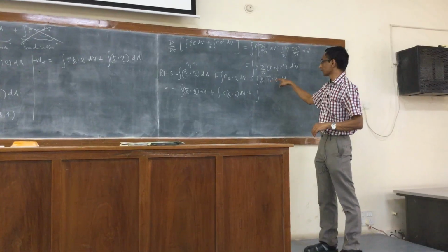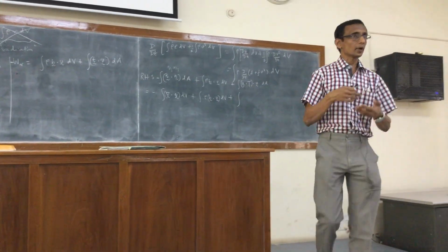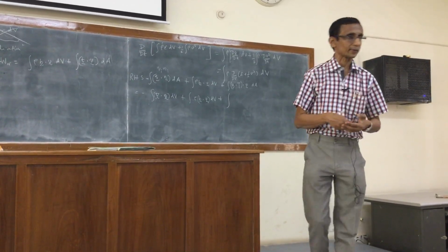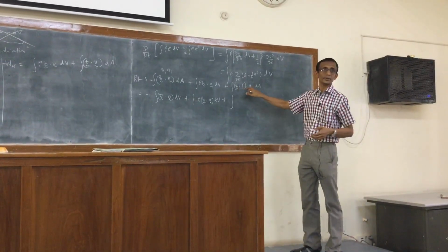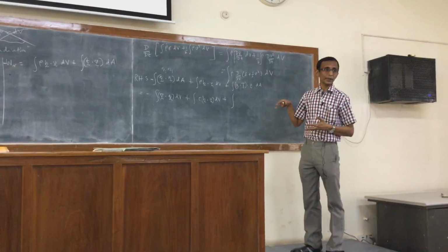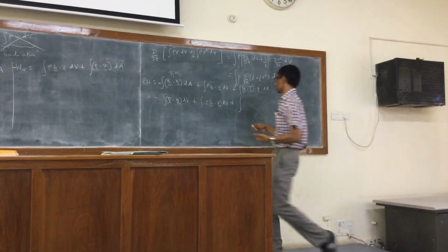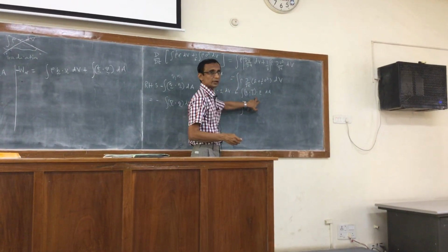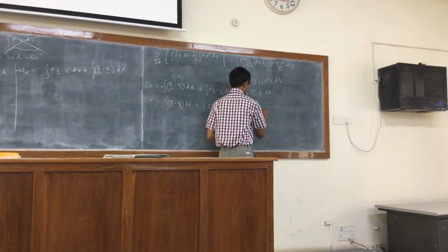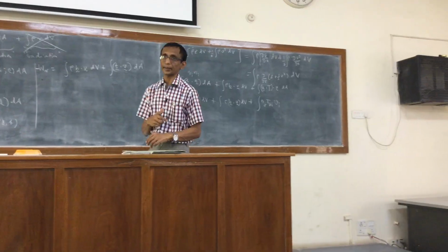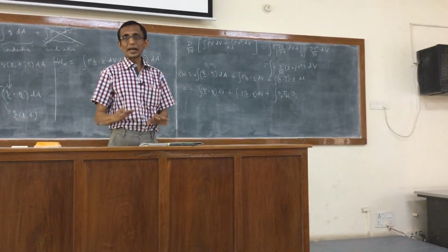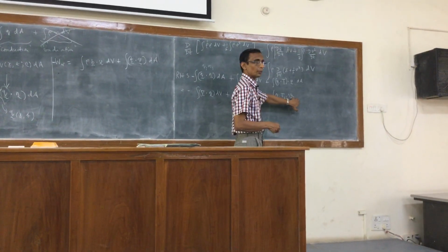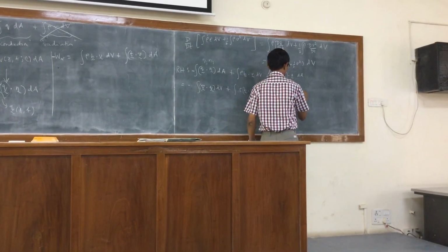So clearly this is a vector, this is another vector. So clearly a scalar dot product of two vectors, one of which is the dot product of a vector with a tensor. So I take the ith component of this, the ith component of this, and then multiply and use the repeated index summation convention. This would be t_ji n_j, that's the ith component of this, times the ith component of the vector v, so that is v_i. And I leave it as it is because it's summed over j, and finally it's summed over both j and i, and this is what I get.